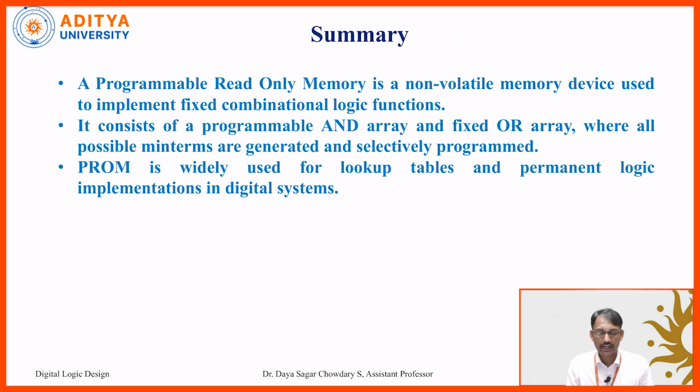Coming to the summary, a programmable read-only memory is a non-volatile memory device used to implement fixed combinational logic functions. It consists of a programmable AND array and fixed OR array, where all possible minterms are generated and selectively programmed. PROM is widely used for lookup tables and permanent logic implementations in digital systems. Thank you.